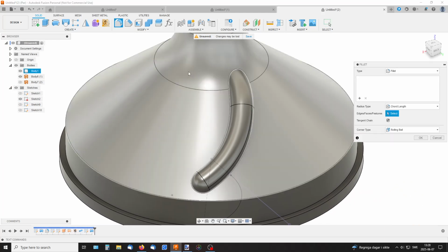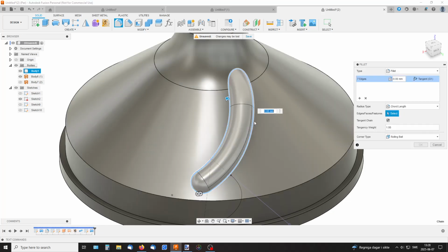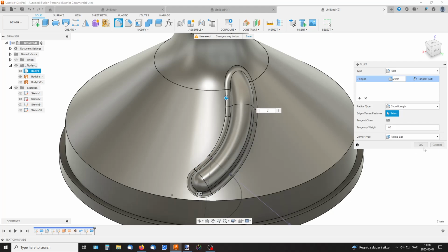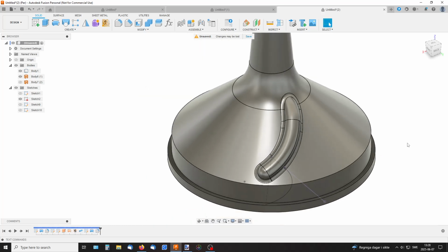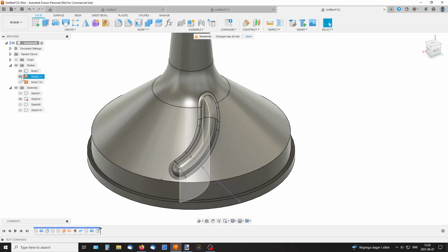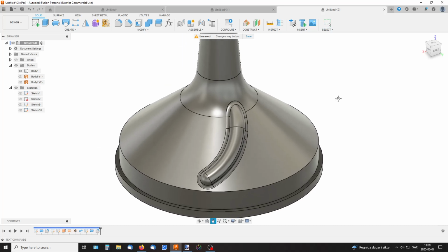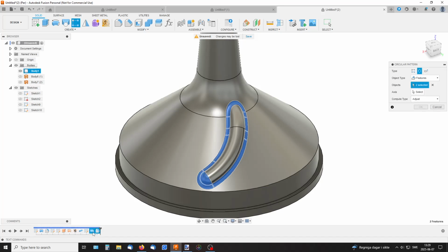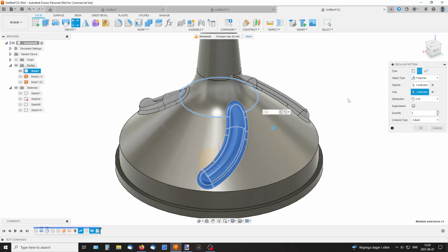So we're close to having made our first. I just need this little fillet there. We can hide our body and let's sketch. And then pattern, circular pattern on features, and select the fillet, the revolve, and the pipe. And the axis, just something that goes around, and quantity, something.